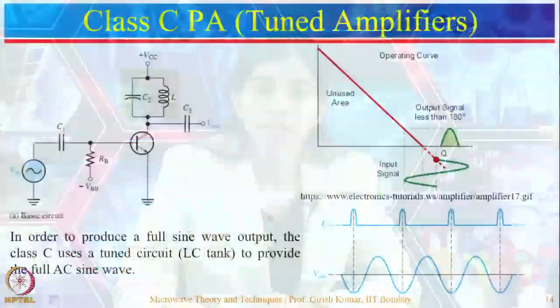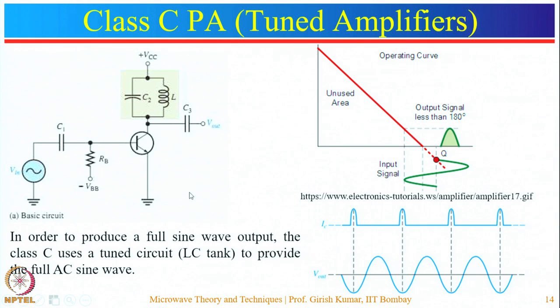The efficiency of these amplifiers is around 95%. So if the supplied power is around 1 kilowatt, then the sinusoidal carrier wave of 900 watt or maybe 950 watt can be achieved using these class C amplifiers, which is a very high value. So the application of these amplifiers is to provide the carrier signal that is of very high output power. So they are used in television signals, in radar systems to generate the carrier signals. This is one of the advantages.